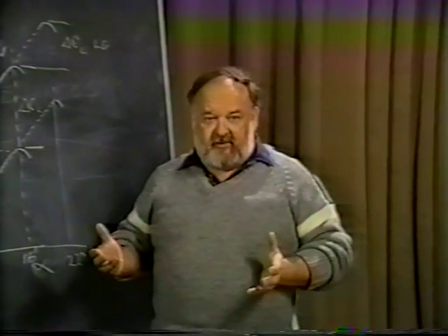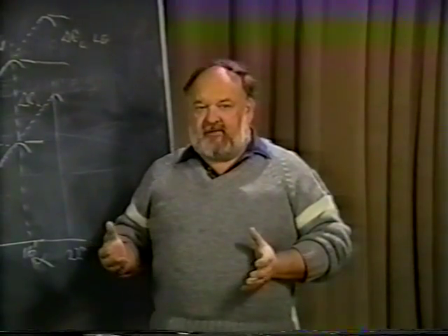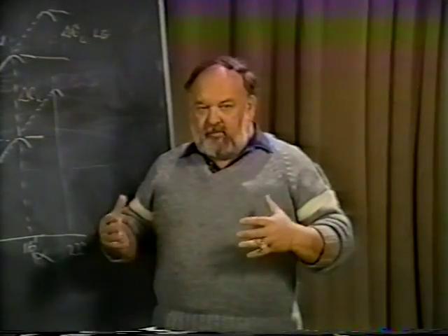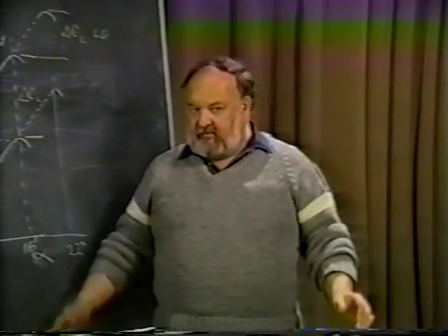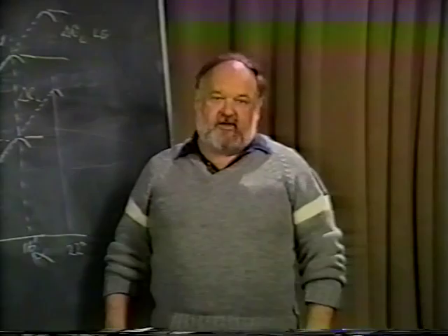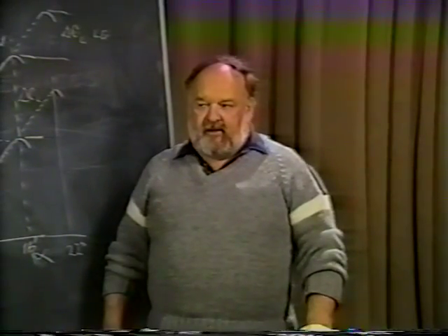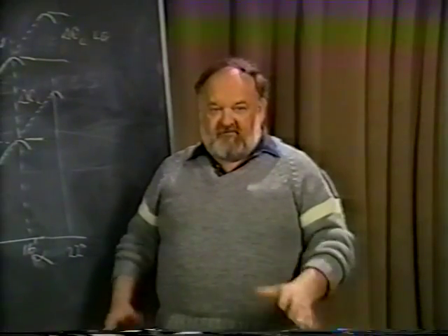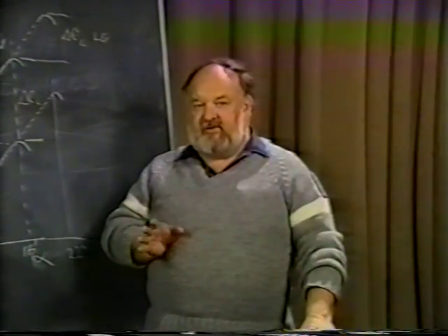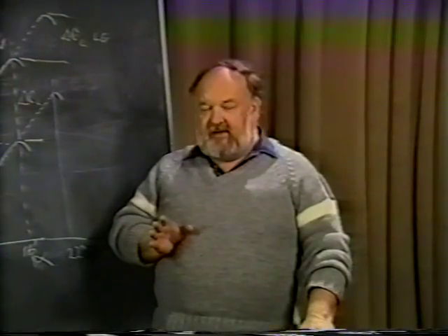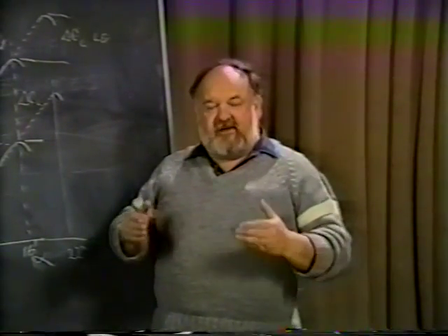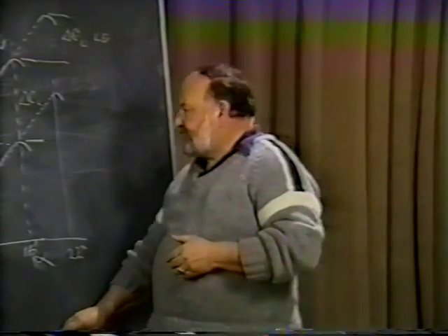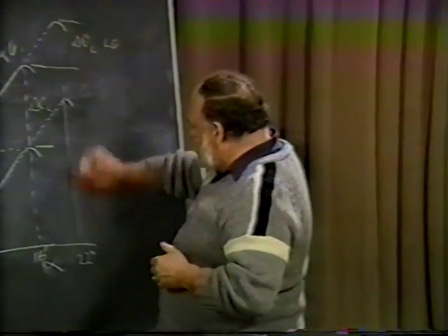An all-flying wing, for example, however, has a difficult time in using the flap, because by putting the flap in the trailing edge, you generally will produce a pitching moment that is greater than what the flying wing's stability characteristics can tolerate. Northrop, when they built the B-35 and the B-49 flying wings, needed to use some form of flaps on there. And what they did, they used a split flap. But even in that case, they could not use the split flap all the way back at the trailing edge. And what they really did do is this.